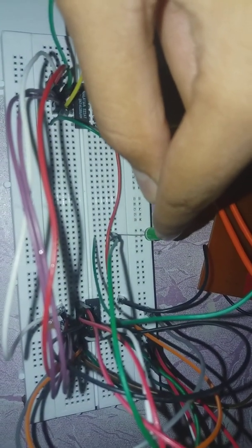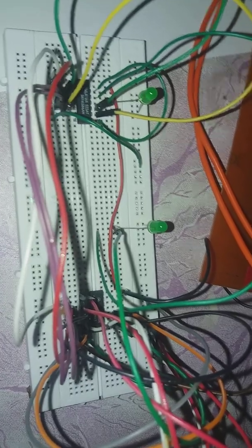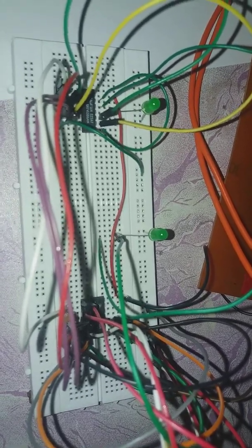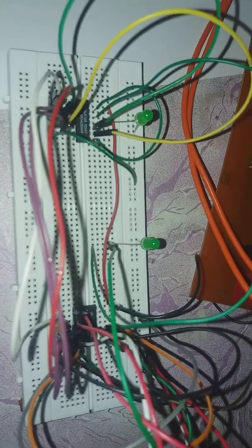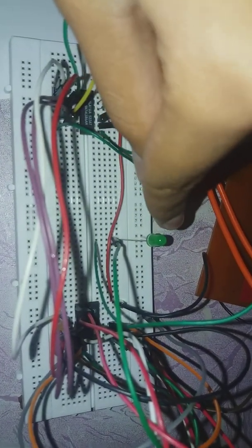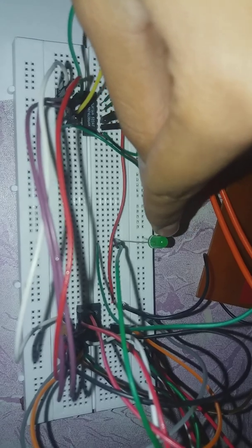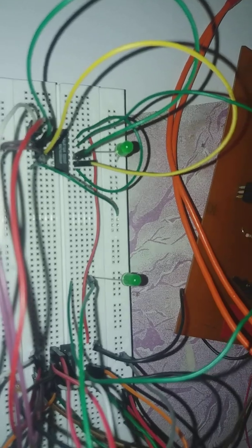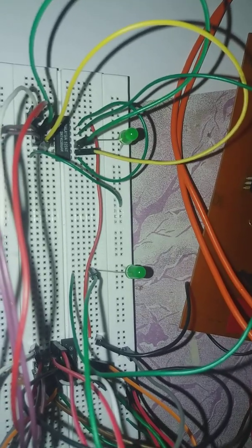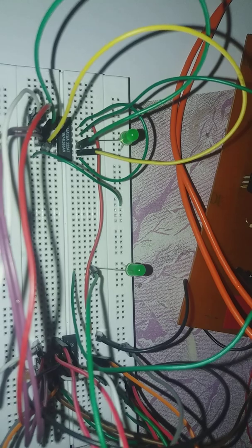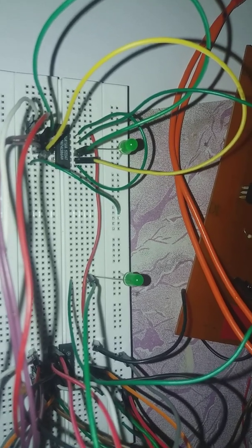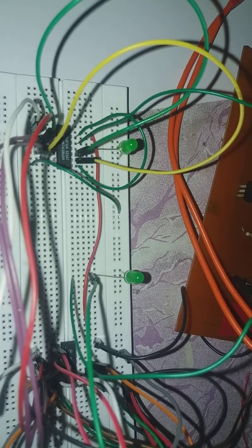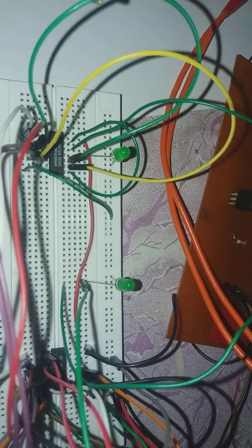That means the new code becomes, for suppose we have given a code of 1000, so the number of ones is odd. So this circuit will create another bit, that is 1, which will be added to the input bits. So the input bits were 1000, and after the output it will become 1001. Now the number of ones is even.